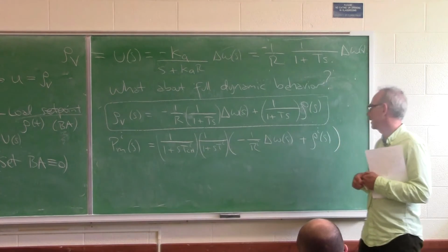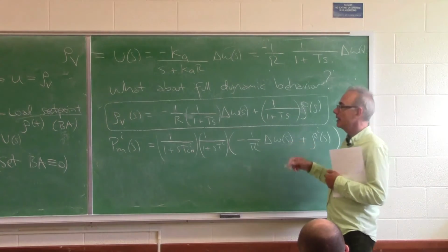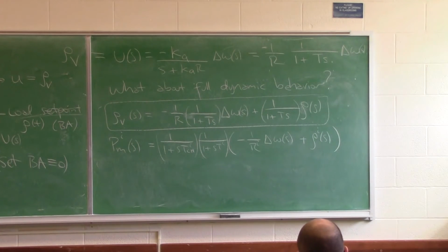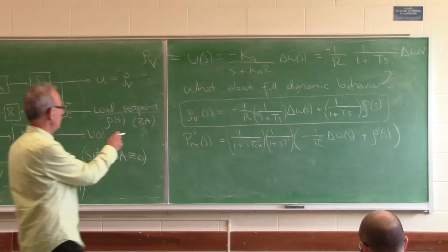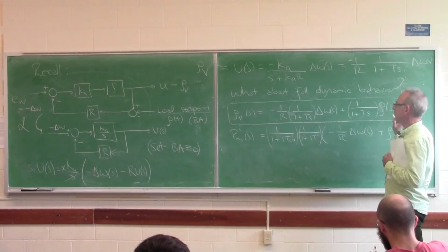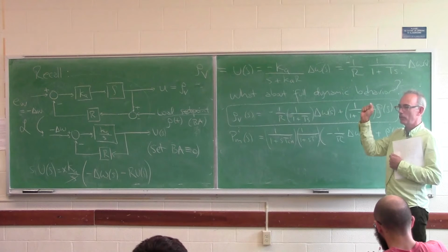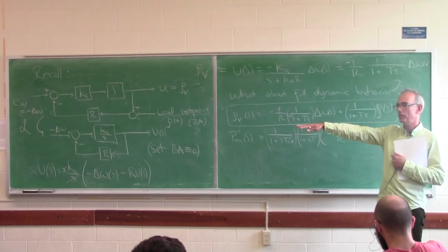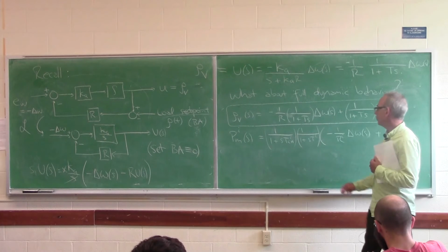But they're assuming here this is a steady state case, right? No, but this is not now. That's why I've got S's everywhere. So steady state means I set S equal to 0. Although here we have rho v equal Pm, it's still not the steady state. No, it was only when I set S equal to 0, when I did computations to say, what if there was somehow an increase in load that was persistent, or a decrease in generation, what would all the variables converge to? That's what we did last time.